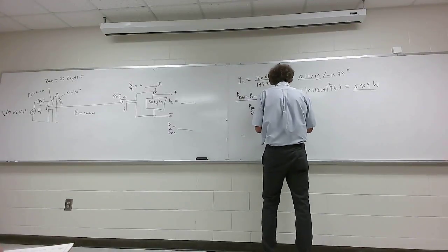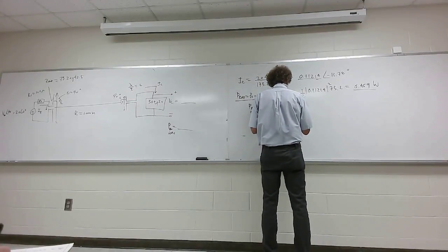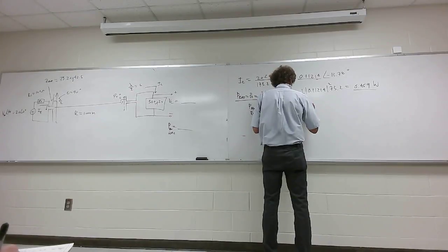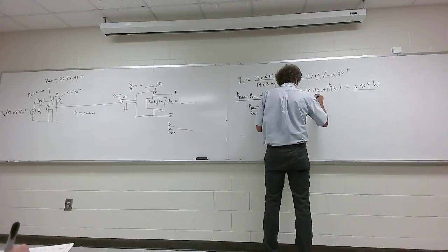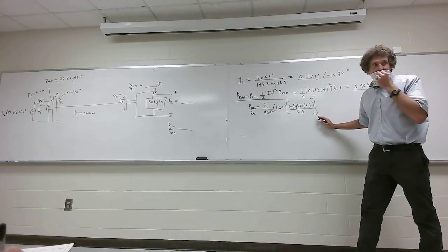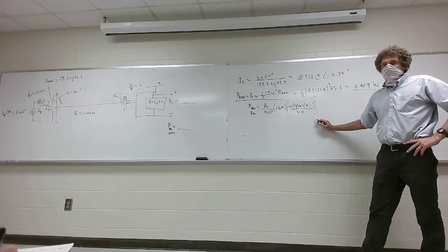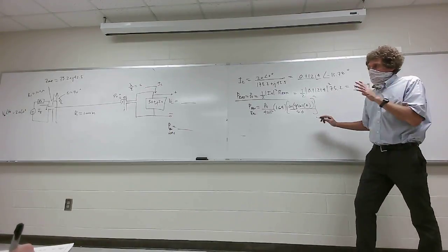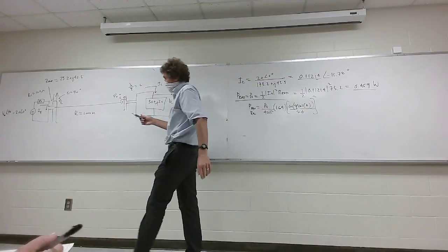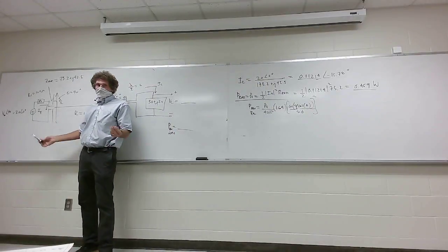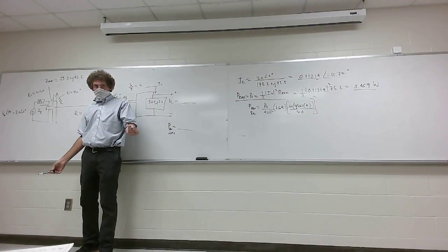Now technically, you don't have to write this down. It's the cosine of pi over 2 cosine of theta over the sine of theta, squared, isn't it? If you give us a problem like this on a test, do we assume 100% efficiency to get 1.64? Yeah, unless, now, here's the thing, if it wasn't 100% efficient, then I'd have to give you something about the resistance of the antenna itself, not the source resistance. You follow me?